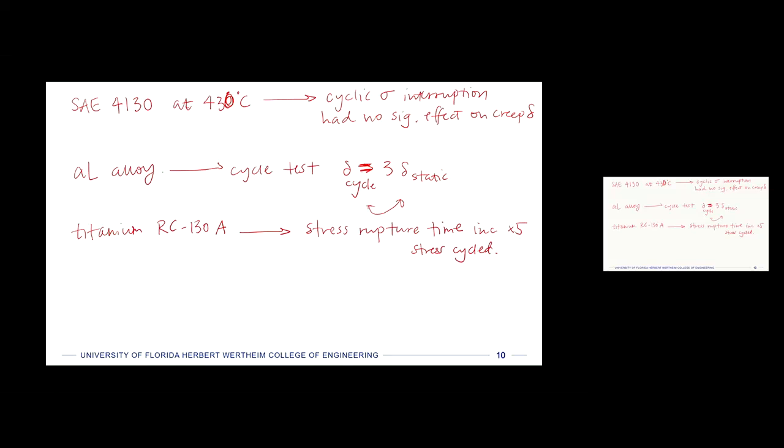So they give us these 3 materials to tell us that the effect can be one of these 3 ways. It can be negligible, and that would be really helpful because then we can analyze our lifetime separately from creep strain. They don't interact. There's no combined effect, and we already know how to do a lot with fatigue lifetime predictions. Now we know about creep, so we just have to see which one will be the limiting factor because they don't interact. We can keep those separate.